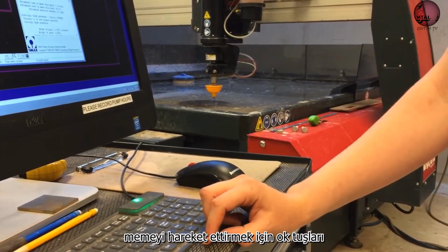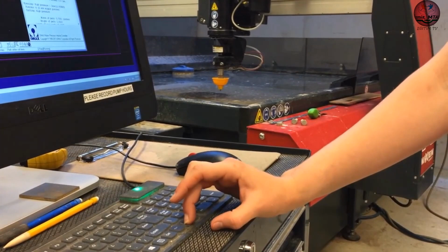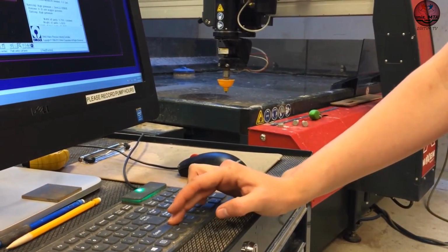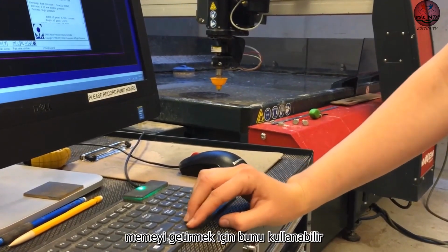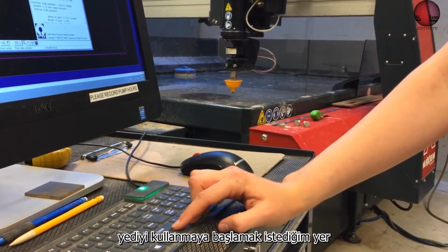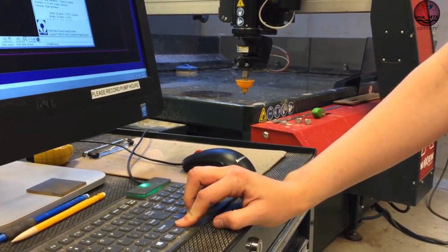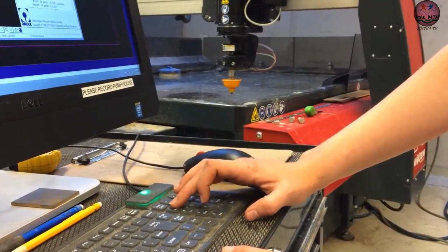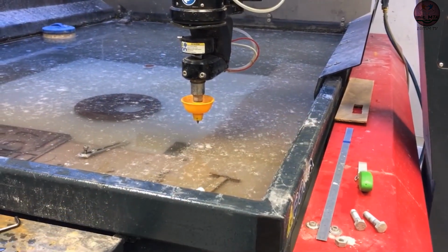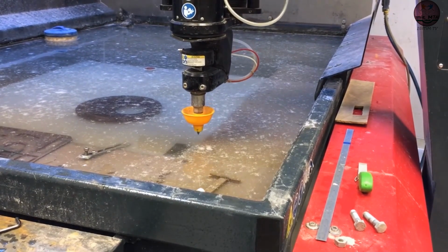You can use the arrow keys to move the nozzle around on the working area. So I can use the down arrow, the up arrow, left, and right. And I can use this to bring the nozzle over to where I want to start. Using the 7 and 1 keys on the numpad here, you can raise and lower the nozzle. You use 1 to lower it and 7 to raise it.